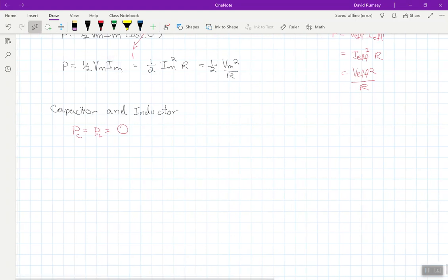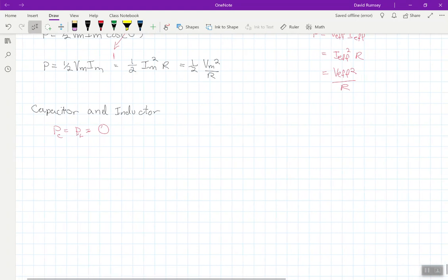It turns out this is going to be something that's called reactive power. And this actually, we're going to notice later on in the discussion of power, is going to become quite important, because while reactive power is real in the sense that it's there, it's not imaginary, reactive power is absolutely present in a circuit, it's not something we can use to turn the crank.